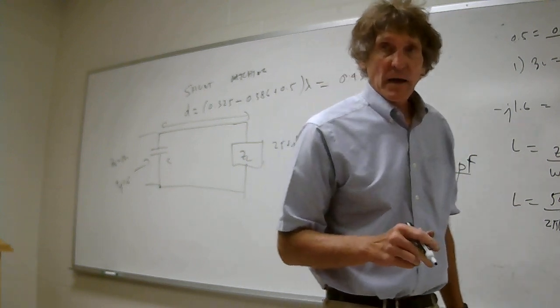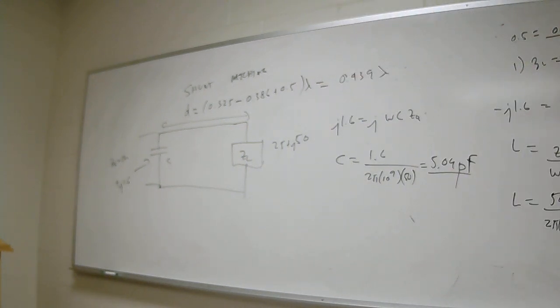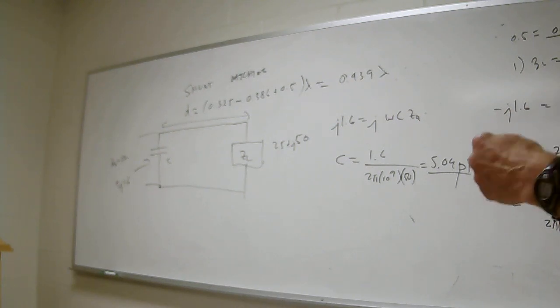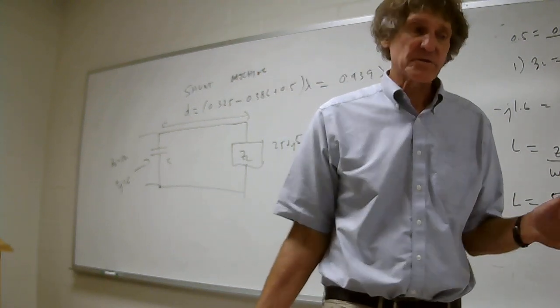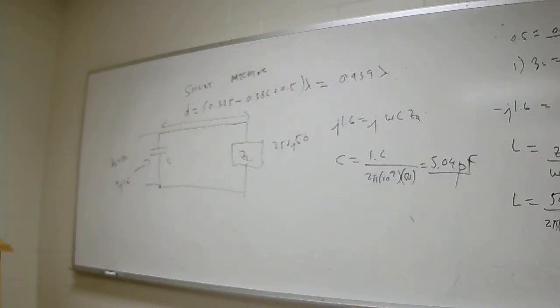Yeah. That's not too bad. When you get sub-picofarad values, you're really dealing with stuff where just the length of wire, if you don't have real short leads, will affect it significantly. When I teach EMC, I teach a lot about compatibility and FCC regs and CISPR and how to meet regulations. One of the worst things to do is talk about something like 0.45 picofarads.